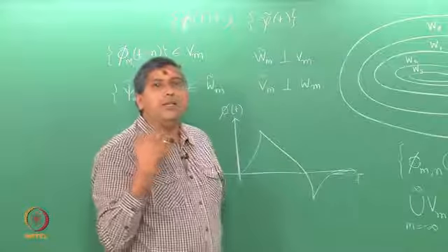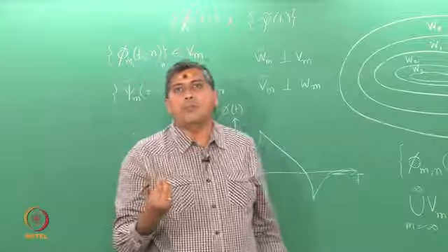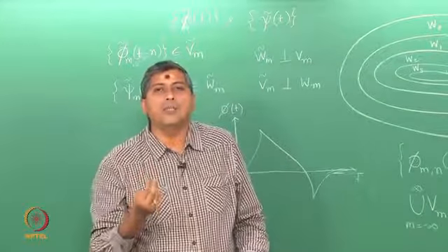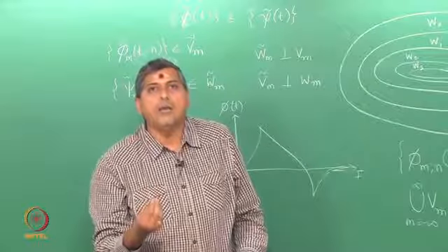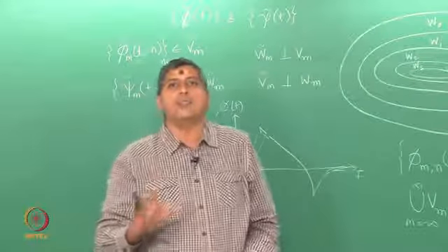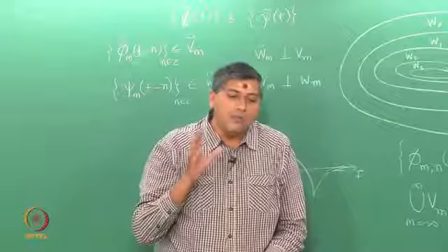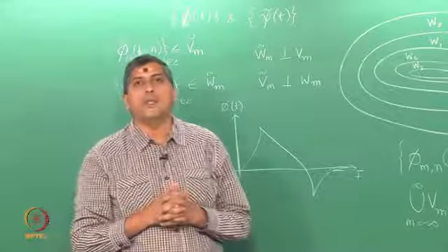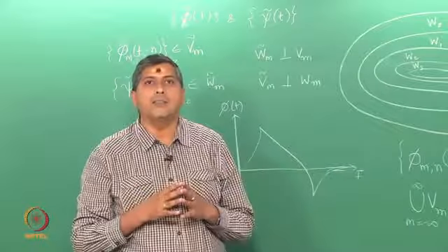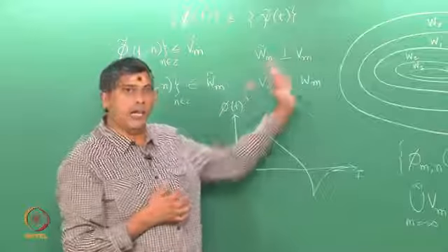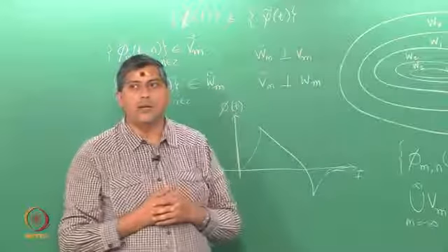Remember, ultimately one of the main applications of DWT is signal compression, and in signal compression we are seeking wavelets that can represent a given signal in as few coefficients as possible. With biorthogonal wavelets, you can achieve this in a much better manner in many applications than orthogonal wavelets. That is because again of the symmetry and the flexibility that you have.